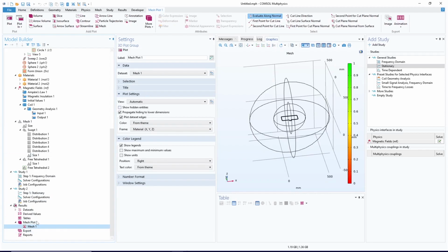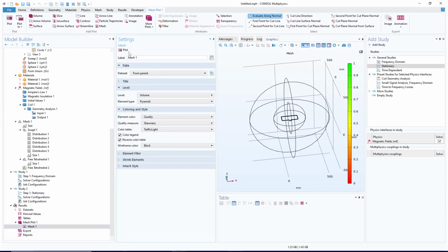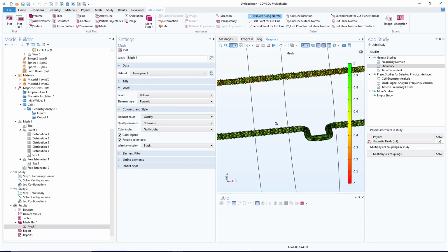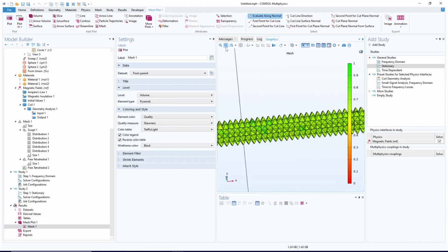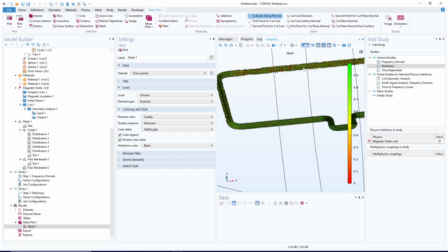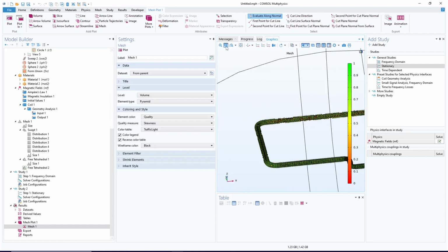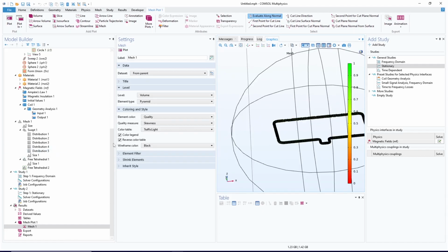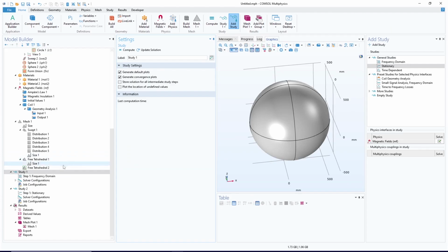And we can see the meshes right now, pyramid. You notice that this part, for which we have changed the distribution, now becomes mostly green. This part we could also improve and make the mesh for this region better. But this is basically the trick. Now we have done the mesh. We can continue to run the simulation.